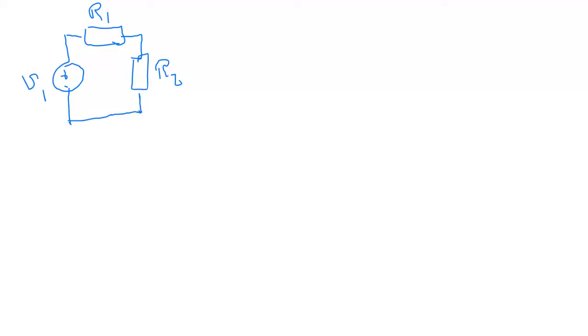Okay, so let's assume that in SPICE we have this: R1, R2, V1. So the first thing in SPICE is assigning nodes. This is ground, so this is node 0, node 1, and node 2. Okay, so in SPICE, we would do something like that.